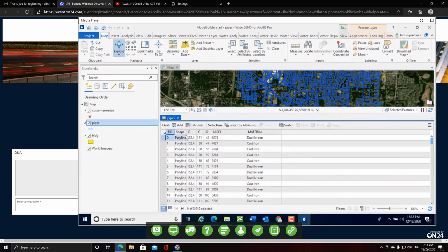So these pipes, the data that's contained in my GIS is the diameter. There's also the roughness, Hazen-Williams C factor there, which I think probably a lot of GIS systems may not have. We happen to have it in this case. It'll work either way. And then we have the material for the pipes.